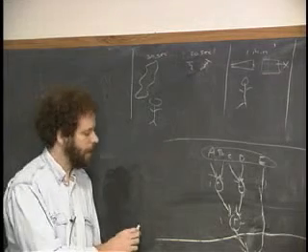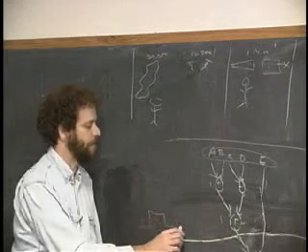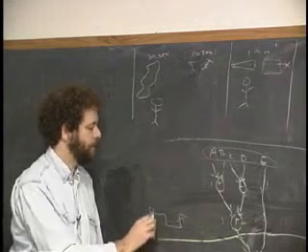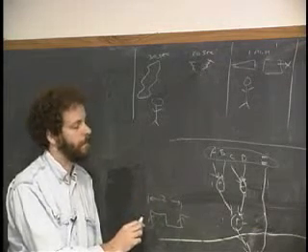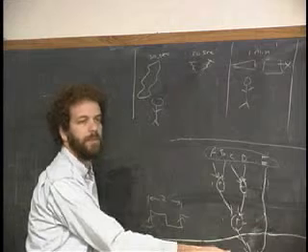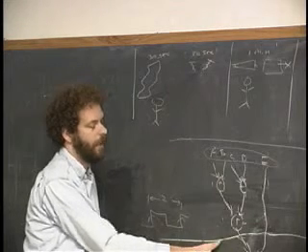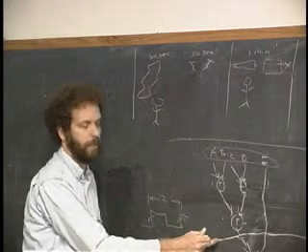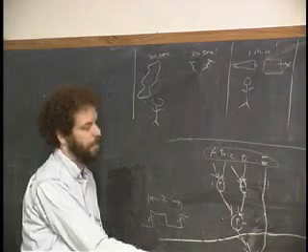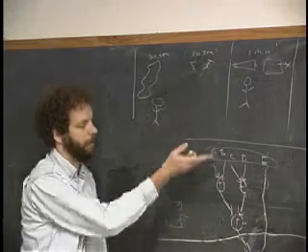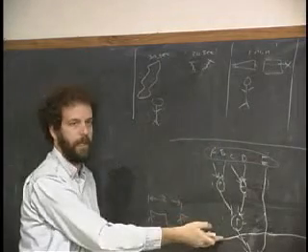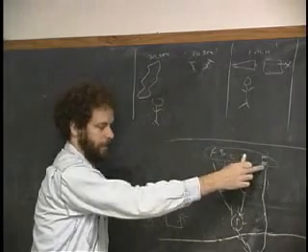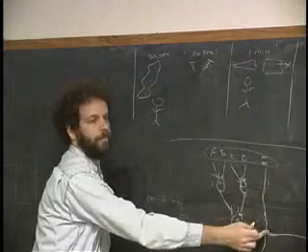In this case, the clock is going off once every 2 time units. So now this time is now 2. And that's because this element I changed to be 2 time units long. So we have to wait 2 time units between when we clock this and when we clock that. And thus, we give 2 time units between when the data is presented here and when we clock it out here. Now, E arrives right away to here.